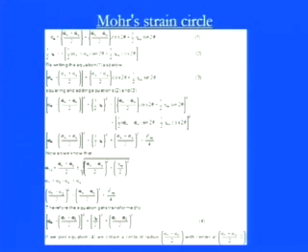This was the first equation, which gives you the direct strain component at the oblique plane, and similarly we can get the shear strain component at the oblique plane, which is gamma theta by 2 equals minus of, because there is a reduction towards the shearing plane, epsilon x minus epsilon y by 2 sine of 2 theta minus gamma xy by 2 cos of 2 theta. So these are the two key equations which give you the two strain components at an oblique plane, one perpendicular to the plane and the other parallel to the plane.